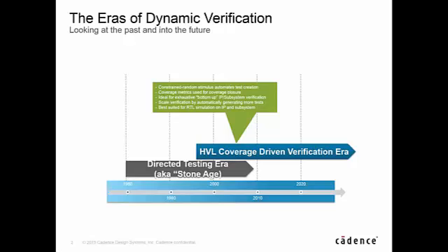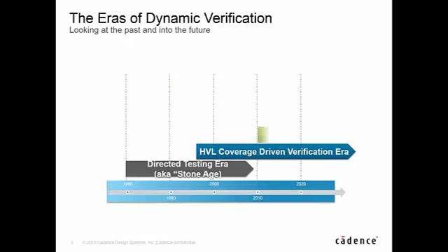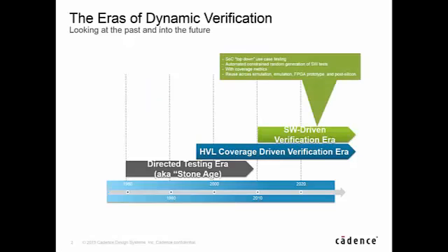But what was found by people using the HVLs is that as you moved up to the system level, it was not sufficient to be able to do SOC level testing. At the SOC level, you also wanted to get back to some of the directed concept, because a lot of SOC verification isn't about verifying everything that the SOC can do, but more about verifying the use cases of how the SOC is going to be applied.